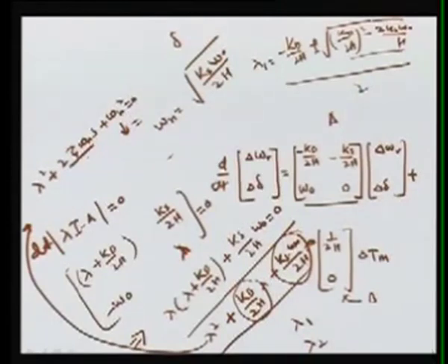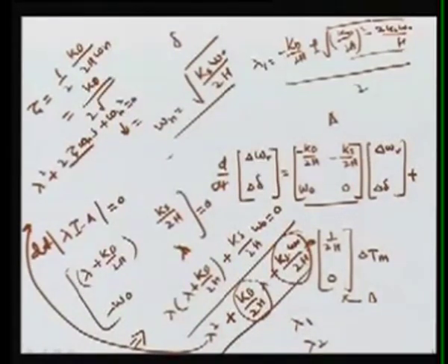These two values will be equated, so we can get omega n from this, and then we can get the zeta. This zeta will be half of kd over 2h omega n, or we can write it as kd upon 2 under root ks twice h omega. So now for different values of kd and ks, you can see your zeta will be changing.